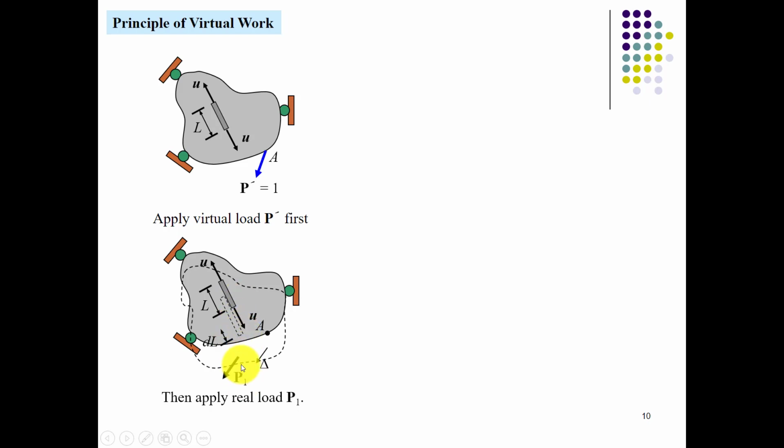You can calculate the delta or strain by multiplying your P1 with the virtual loading. So here is a delta load, delta internal energy and delta external energy. What basically is delta? Delta is the amount of work done by the action of a force, when the virtual force has been applied.